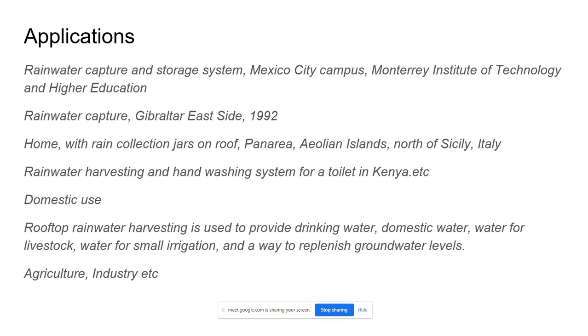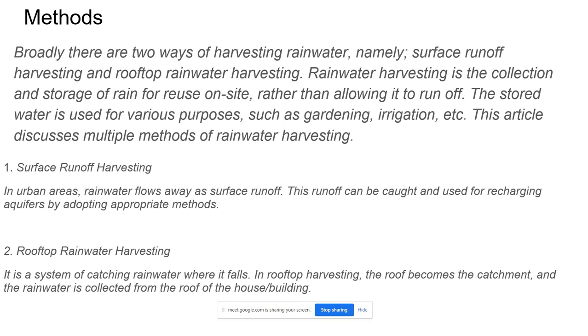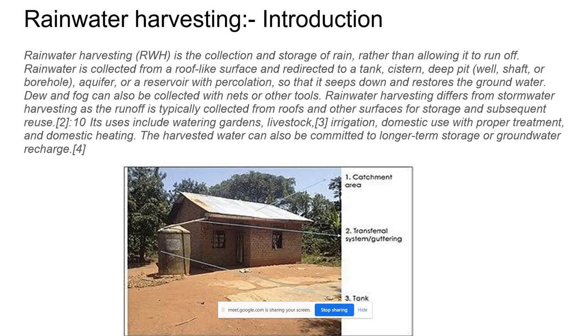Like if we develop water sense level irrigation control, a type of smart irrigation control technology that uses local weather data to determine when and how much to water, and soil moisture sensors for watering plants. Also sprinkler heads or micro irrigation or drip irrigation are generally more efficient than conventional sprinklers because they deliver low volume of water directly to plant roots. Thank you, ma'am.